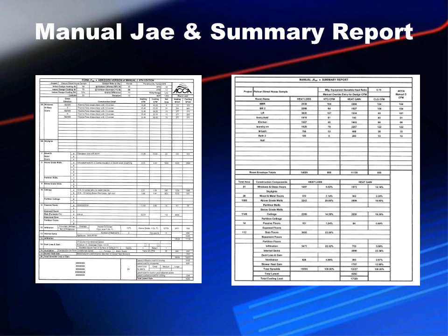The summary sheet will print out all the bedrooms, bathrooms, and rooms in the house and what the CFM value is for each. If you want to put in an override and plug back in a CFM once you do your equipment selection, it'll automatically change all those numbers to match your equipment selection, so you don't have to figure out how to balance it again. It'll all be figured out for you on the sheet.